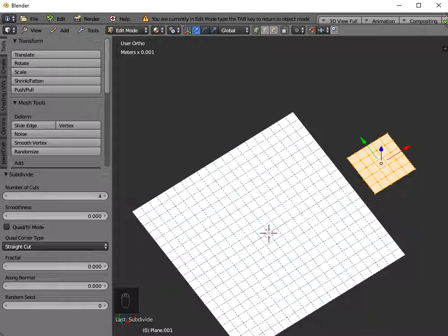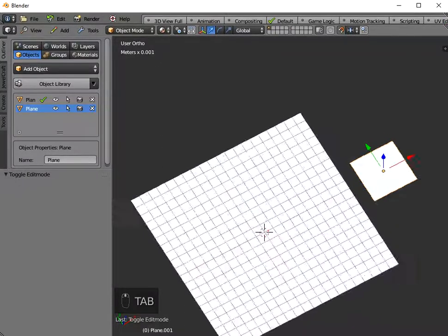I don't really want to make anything smaller than that because I want to be able to know that it's going to 3D print. If you go to 5, 6, certainly if you go to 7 and 8, you can't guarantee that every single element is going to print unless you're really careful. So I would recommend for beginners, stick to 4 or 3 or 2. Don't go mad over here on the right hand side. Okay, so once you've done that, you can come out of edit mode.